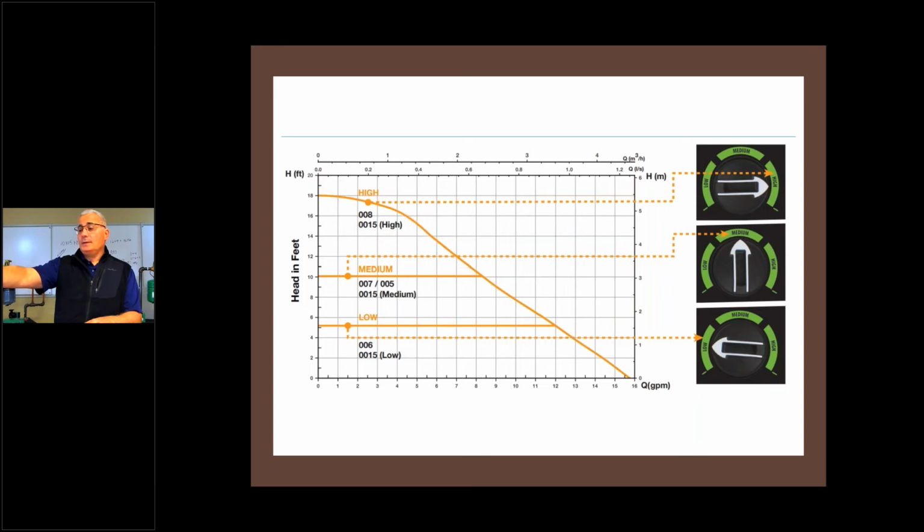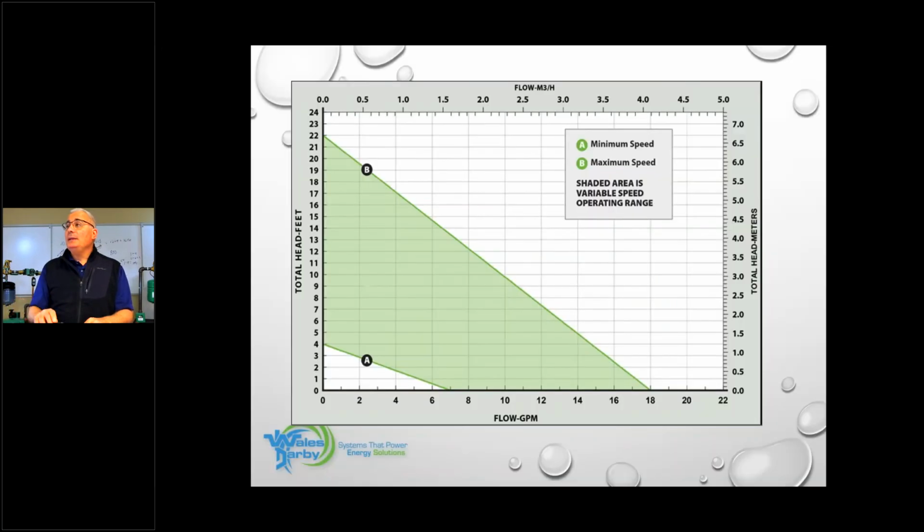That's the way physics works. And I'd also be running at my highest amp draw, again, 44 watts. But a great item for you here, a great service pump to also have on the truck. So if I'm replacing a circulator for a zone system with circulators, I can dial this down and get it really nice and tight to where I have to be. Or if it's just going to be one system circulator, there's a very good chance residentially this would be the circulator of choice. All right, next would be my Delta T, the VT2218.